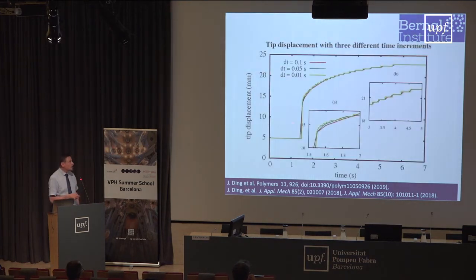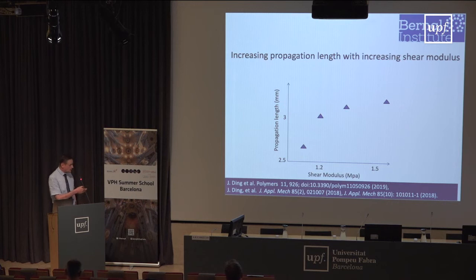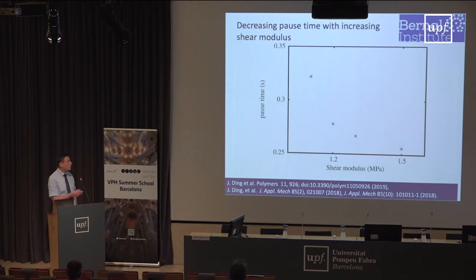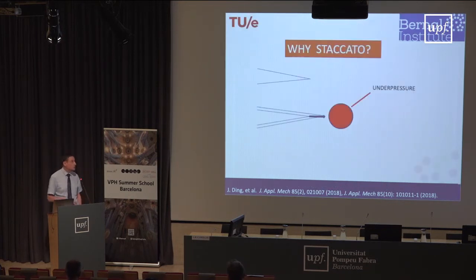And what we find spontaneously is that our system predicts stepwise propagation. It does not propagate continuously, but stepwise, despite the fact that the material is strictly homogeneous. We also find that the propagation length between the different teeth is increasing with shear modulus, which is consistent with experiment, and also the pause time is decreasing with increasing stiffness. So also there we find consistency, at least qualitatively, with what's happening inside the gel.